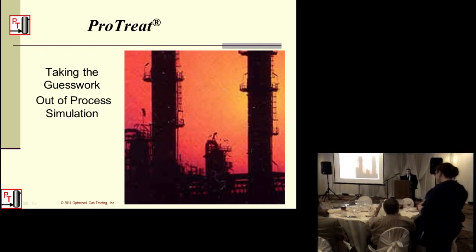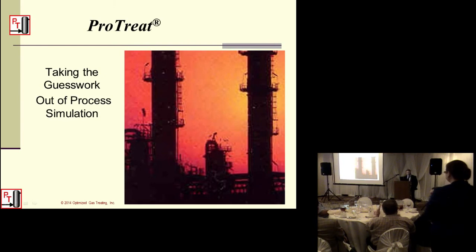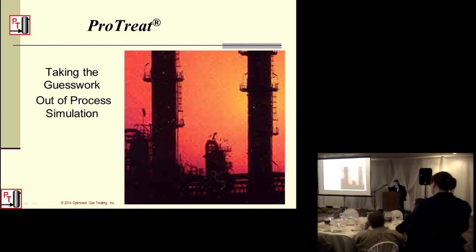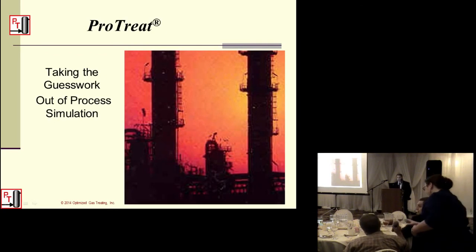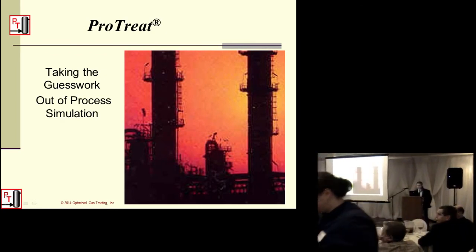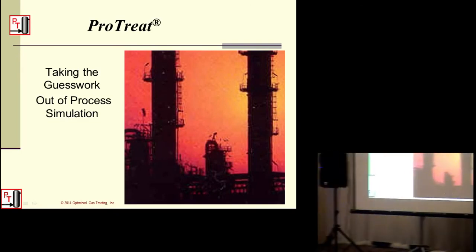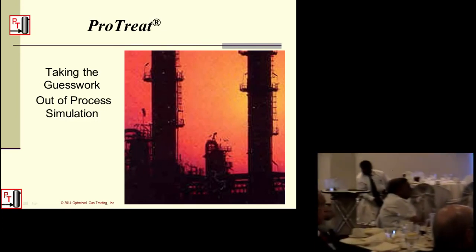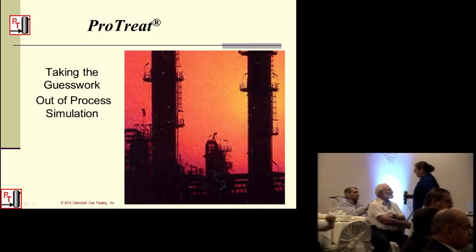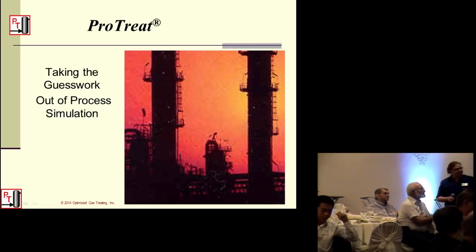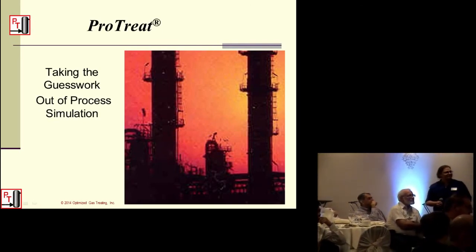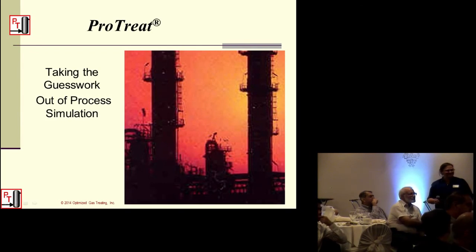The reactions that you were talking about, they're occurring in the gas film. Is that correct? Or these are liquid phase reactions, actually. Liquid phase reactions? Yes, sir. Yeah. But they happen right near the film boundary. In the case of CO2, the hydrolysis with water is slow, and that's what controls the mass transfer rate. Wasn't trying to make gas treating specialists out of you tonight, but there's some more subtle details there. Go ahead.